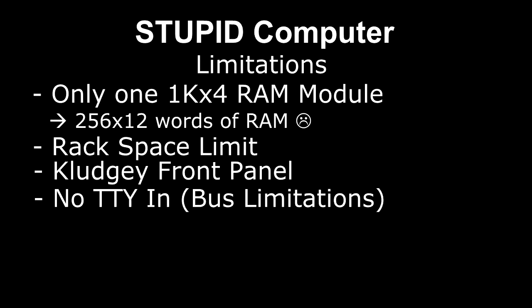So the A bus, I used a 4-input multiplexer. The B bus, I actually used a 2-input multiplexer, even though you see 3 inputs in the block diagram. So one of those inputs got tossed, and it was the TTY input, which, as I mentioned earlier, there was no TTY, no keyboard available. So you had to do all your inputting, even if you're running a program, through the front panel switches.